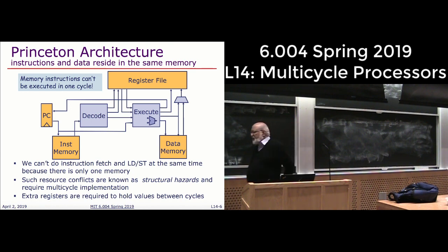And so what that means is an instruction is not going to execute in one cycle. So I execute the first cycle of the instruction and now have some temporary information which I have to remember until the next cycle when I finish the execution of the instruction. So these two ideas go hand in hand. The moment an instruction is going to be multi-cycle, there is going to be some registers yet to be defined, right, which will hold the temporary information that you have generated in cycle 1 to be used in cycle 2.